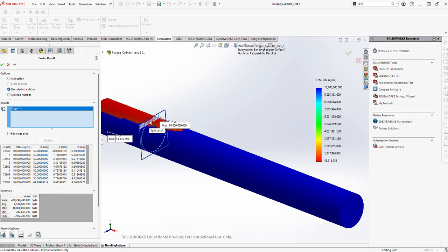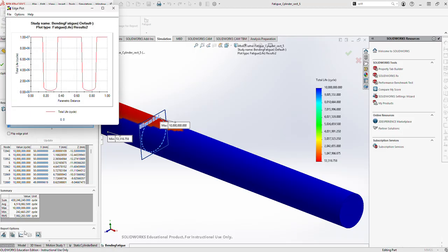And then based on the area of interest that we have defined, we saw that the minimum number of cycles in that area of interest is 242,663 cycles. So basically, that's on this, which you can also read directly from this plot in the region of interest. So it's around 267,000 cycles that you're seeing here, or actually roughly around that.